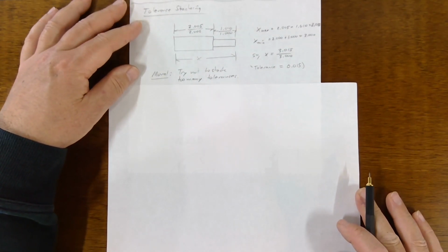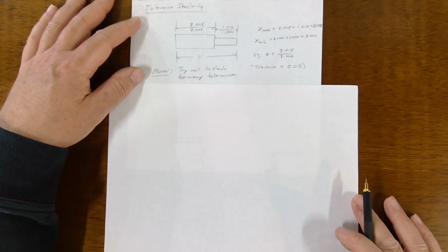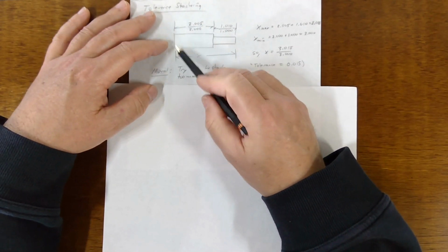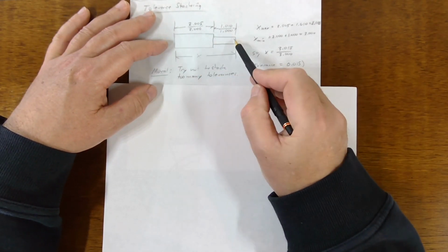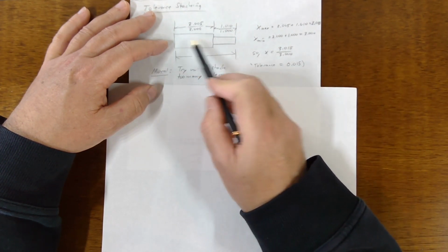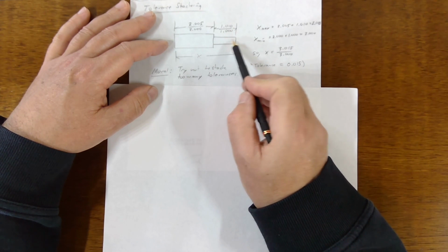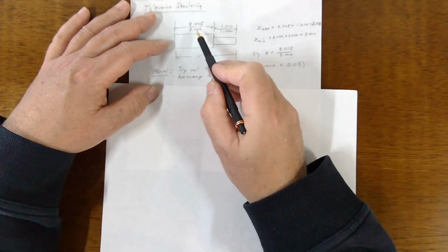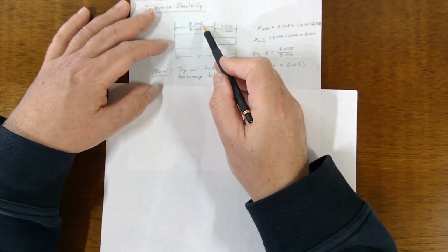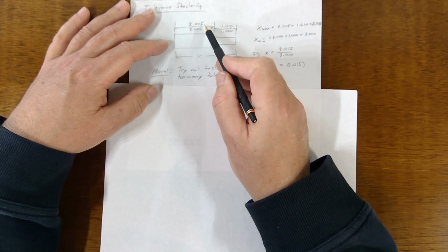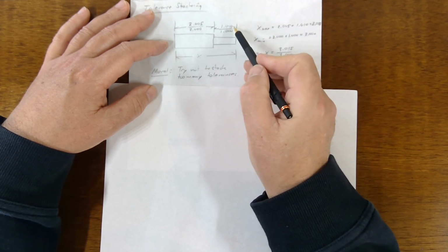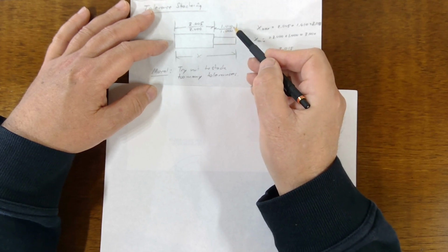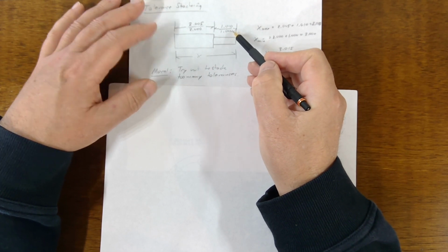Sometimes we have several tolerances together that add up. We call that tolerance stacking. Here I have a little part with a fat part right here and then a skinny part right here. This thing is approximately 2 inches long. And this part over here, the part that sticks out, is 1 inch long. Both of these lengths have a tolerance on them. This one is 2.005 over 2.000, so it has a tolerance of 5 thousandths. And this one here has a tolerance of 10 thousandths. Biggest value is 1.010, smallest value is 1.000.